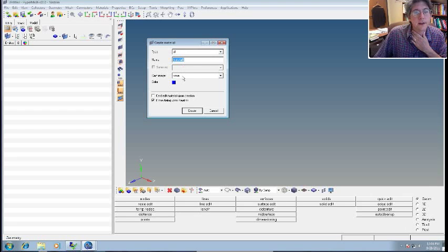Since we're in the Nastran mode, user profile, you can actually pick from the various Nastran material cards. Now we've only used Mat 1, so we'll define a Mat 1 card. So you can see it knows the different Nastran materials. If you had it set to Abaqus, you wouldn't see Mat 1. You would see whatever selections are available for Abaqus. Here you can give the material a name. Let's just call it, we'll make it out of aluminum.